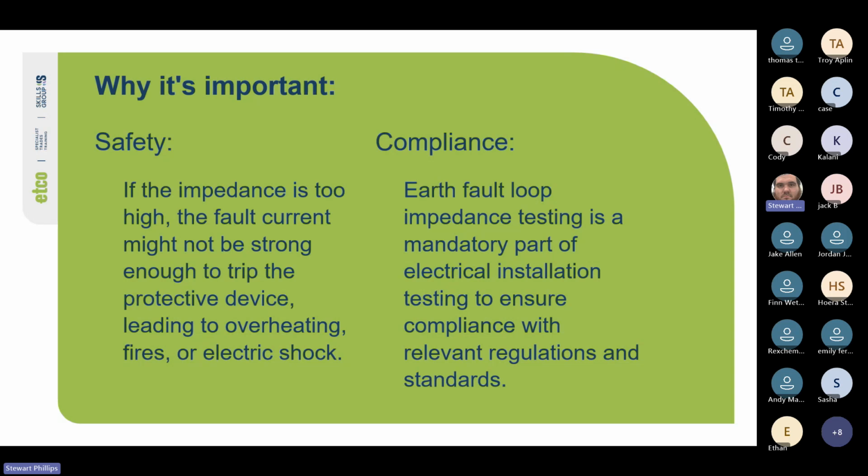If there's a fault in the toaster between phase and neutral, your RCD only protects against earth fault loop or earth leakage. It can't protect much against short circuits, but it's good to know that your circuit breaker is going to trip, just in case the RCD fails.